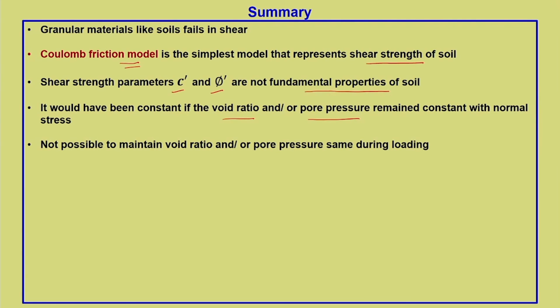So, it should not lead to confusion. It has been said there it is decoupled, why is it not decoupled? It is decoupled in that mathematical framework, but it is difficult to decouple to understand the behavior of soil, because there will be volume change. Now, if the shearing had happened at constant volume, probably C dash and phi dash could be fundamental parameters, which we are not able to achieve. Either the volume change will happen or the pore water pressure would change. So, this prevents the phi dash component from being a fundamental parameter.